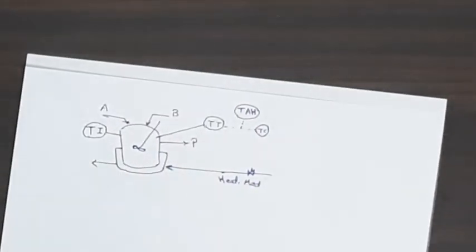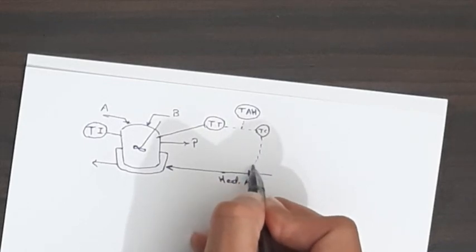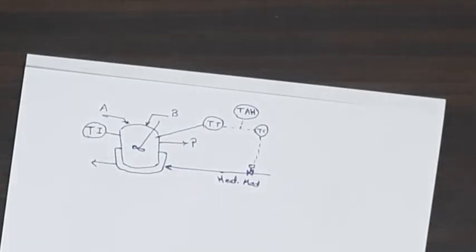If the temperature is low, then the flow rate of the heating medium will be increased. The temperature controller sends an electrical signal to the flow control valve. This is the scheme. The third one is an assignment. You need to draw it, and indicate the controlled variable, manipulated variable, and final control element as well.